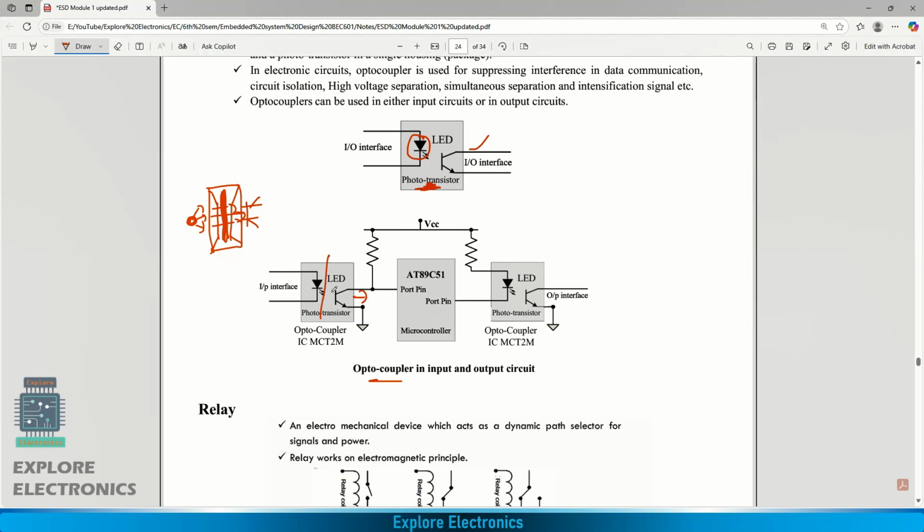So these kinds of optocouplers can be used to detect something which is blocking the region of the LED as well as a detecting system. Then it is connected to a microcontroller as well. Suppose if the data is broken, it will take some action from the port, and again the same kind of optocoupler is used here to transmit the signal.